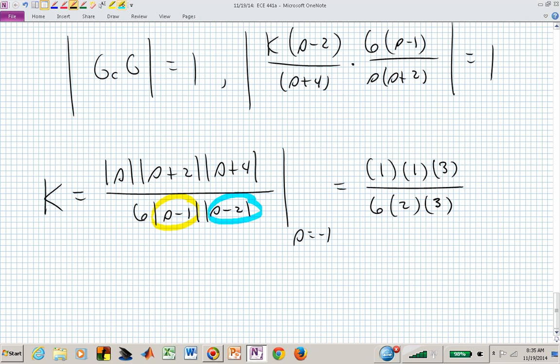This one is there, and this one is there. And that's not too hard to compute. K of 1/12 is what I want. So I'm not cranking up my gain very high, and I'm getting one of those poles to -1.